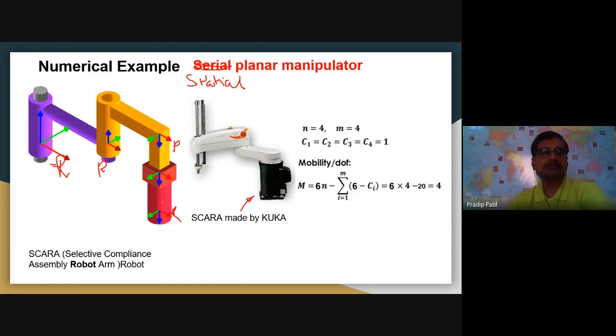So this is a revolute pair because it can rotate like this, so we can use it for orienting. For example, if I approach my mouse with this, but it is not exactly arranged, so I can go and pick it properly. So we can apply it to the mobility of DOF, that is spatial manipulator.